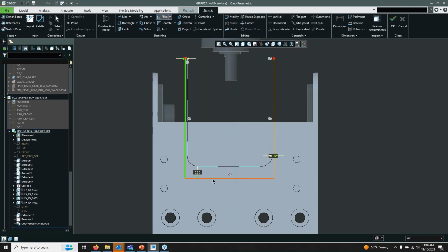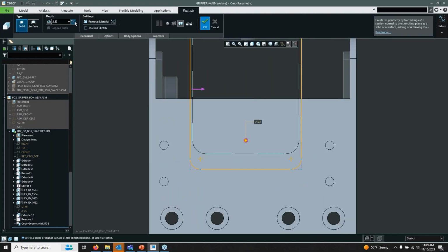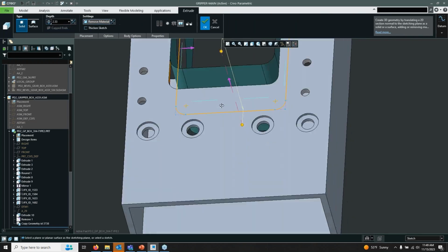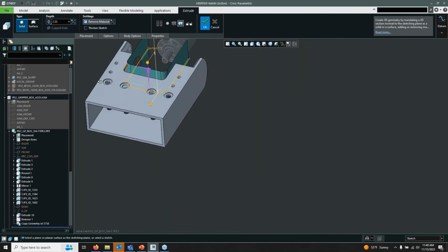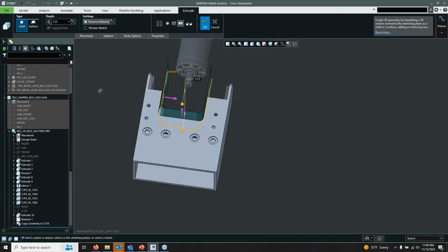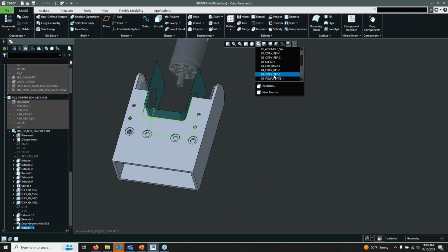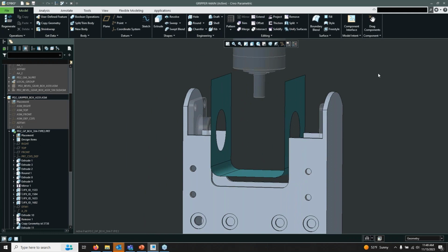I'm just going to do some sketch work, use my corner tool to extend these out. I'm going to make some fillets here. Make these equal size, and then I'll set my dimension. All right, looking good. And we can see how this cut is going to work. It's going to cut right through this component at a constant offset from my SolidWorks part, or from my copy geometry rather. Okay. Good.